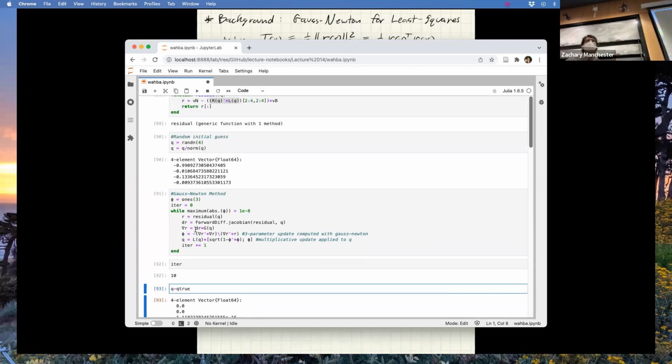Basically the story is Newton's method is a local method, so you're going to converge to whichever one is closer to your starting guess. You can't say a priori which one that'll be. Both will minimize the residual, right? So both are the right answer. But this is a thing you always have to worry about when you do practical control. For example, when you write down your cost function, you have to make it have local minima at both Q and minus Q. You have to be a little smart about this. Otherwise, you can get stupid behaviors.